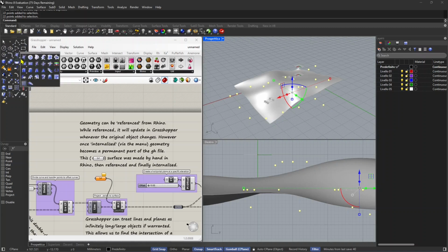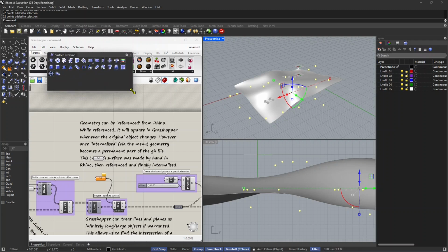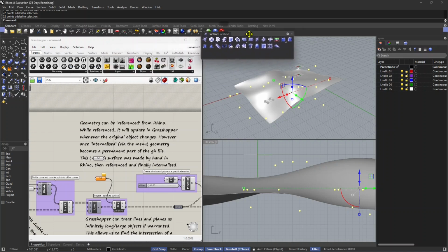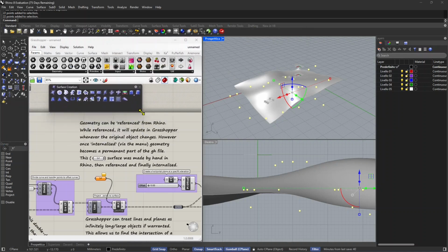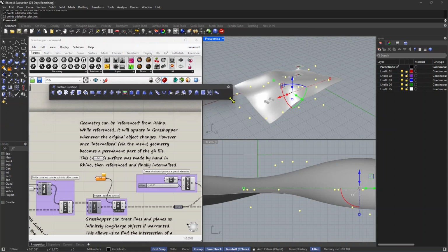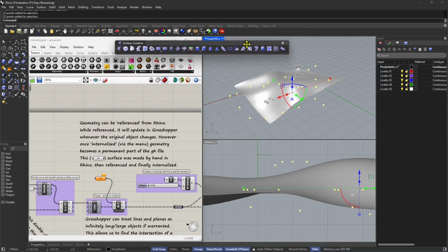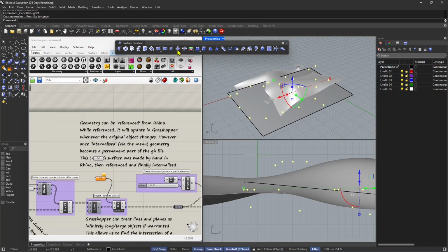So click on there, and the little arrow on the bottom right corner is going to expand the surface toolbar. I can extract it, I can undock it, and then I can expand this, and I can put it somewhere in my interface. I can dock it again somewhere, or I can just leave it floating. Many times I leave it floating. I like it floating like this. So when I'm working on something, I usually bring out the toolbar and I leave it like this so I can access this quickly.